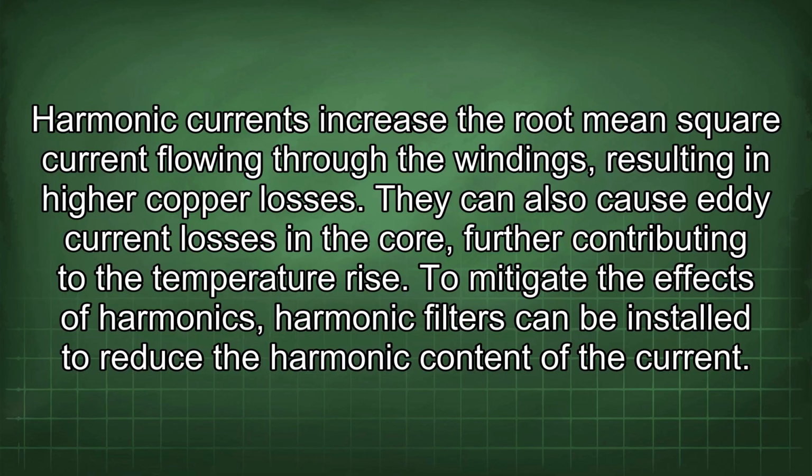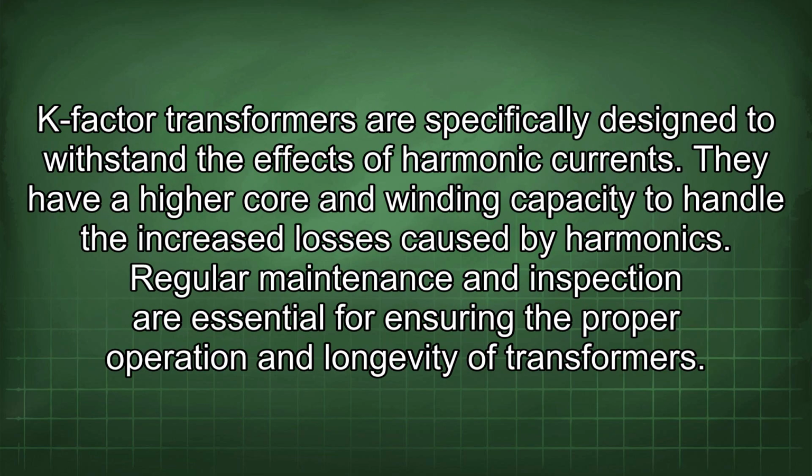To mitigate the effects of harmonics, harmonic filters can be installed to reduce the harmonic content of the current. K-factor transformers are specifically designed to withstand the effects of harmonic currents. They have a high core and winding capacity to handle the increased losses caused by harmonics. Regular maintenance and inspection are essential for ensuring the proper operation and longevity of transformers.